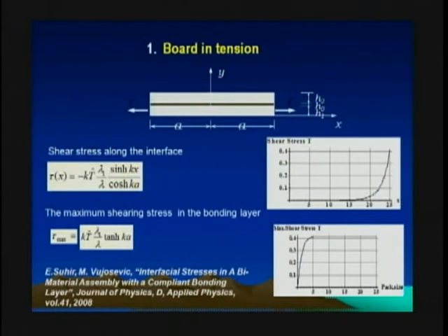On the other hand, in the other extreme, where the interfacial compliant layer is not compliant but ideally stiff, in this case, in the mid portion of a long enough assembly, the forces will first be distributed proportional to the axial stiffnesses of these two components, well known.